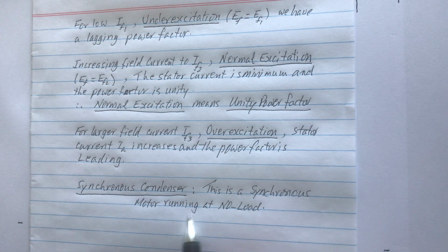But normally we drive it overexcited at leading power factor to improve the overall power factor. So you can use the synchronous motor at no load. This is used in transmission lines.